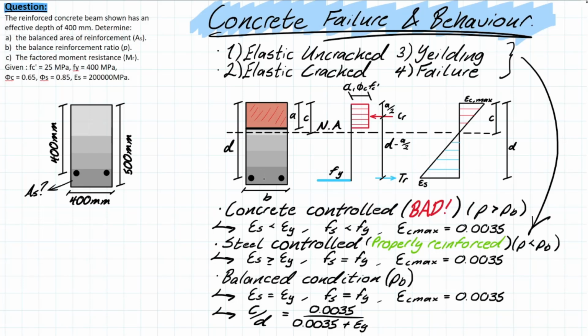All this means is that the stress created in this bottom tensile fiber is exceeding the rupture strength of the concrete. So that FR that we talked about in our first video on concrete design is being exceeded. So now there's cracks that are beginning to propagate, and the concrete area for those cracked segments should now be neglected, meaning that the steel is going to be responsible for taking that tensile strength. But an important point for this phase is that we are not yielding the steel yet. We're just simply having this concrete experience cracking before that yield occurs.